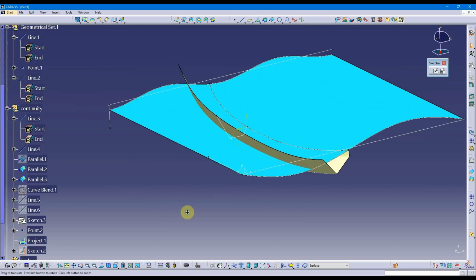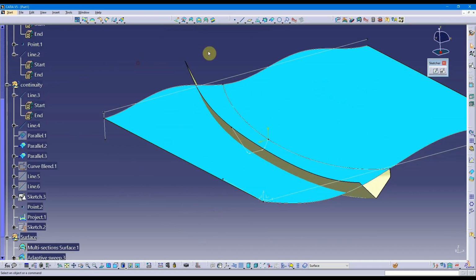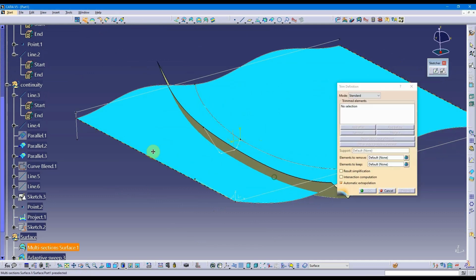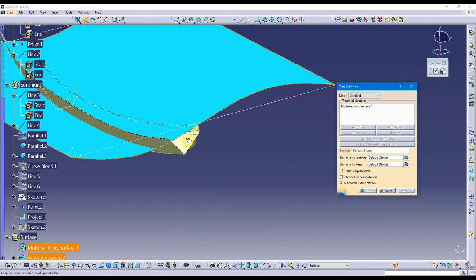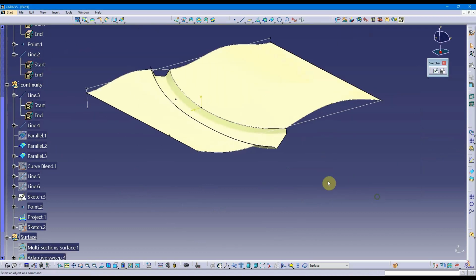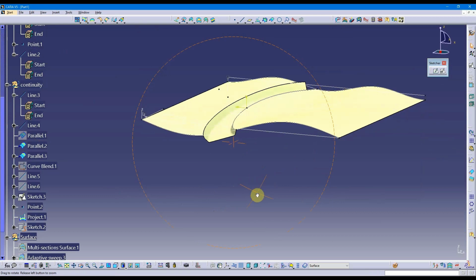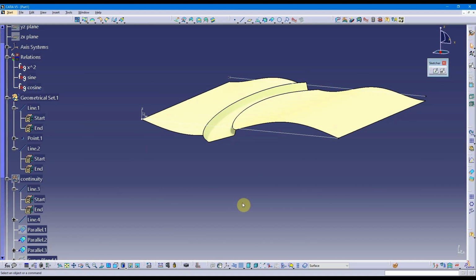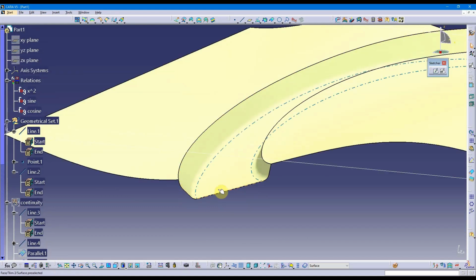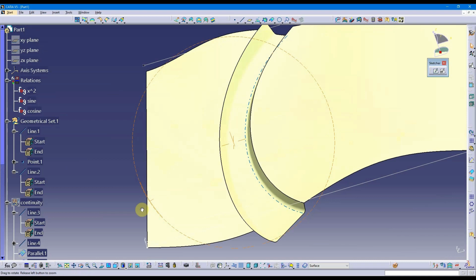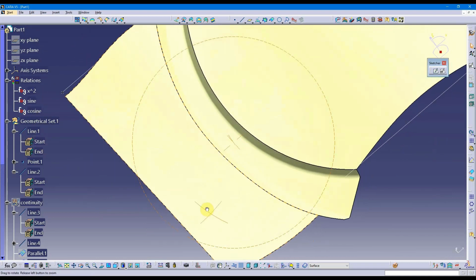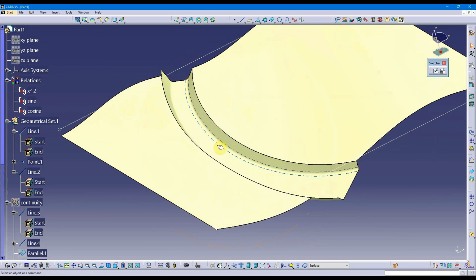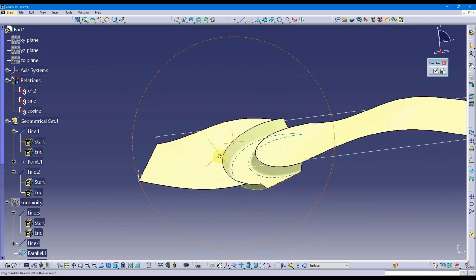So what I can do with this is I'm going to do a trim. So I can trim off there and there, and there's my surface as it sweeps through. You can kind of capture, I wanted it to get wider and more shallow with 3 sections, and the 3 sections I put in were just points on the curve. I could put in more points on my curve if I wanted to and have those.